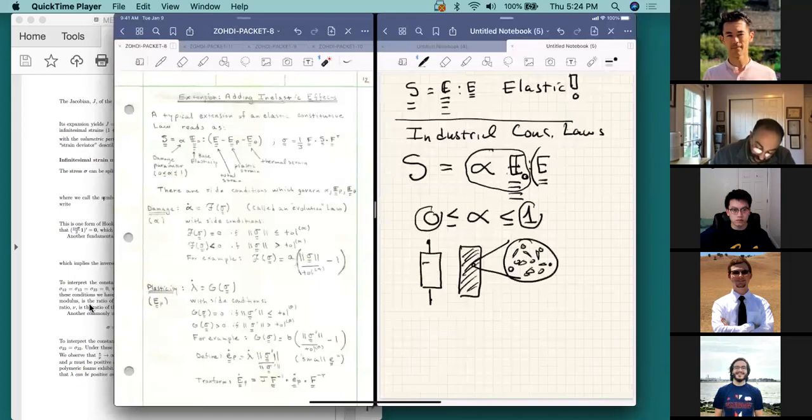So this material might have initially the stiffness E0, but after it goes through this motion or deformation of being pulled apart, the first easiest way to describe this is to simply say, whatever the material law is, we're now going to simply reduce it by the amount of cracks that exist in the material. So sometimes what is done is they correlate this alpha with the so-called crack density of a piece of material.